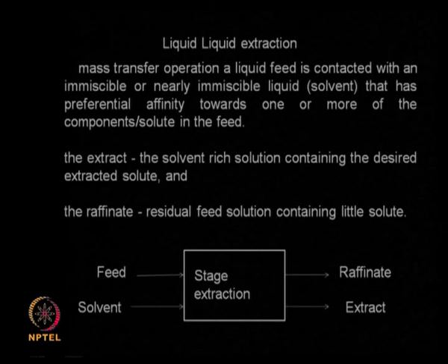So you have a liquid feed, it could be a fermentation broth or a reaction broth which contains the solute or metabolite or the protein which you would like to recover. You use a solvent, the solvent is immiscible or very sparingly miscible, and this solvent will extract preferentially the solute of your interest. You cannot say that only one solute will get extracted, because after the end of the fermentation broth you may have a large number of metabolites. So you may have some of the unwanted metabolites also getting extracted, but that is possible.